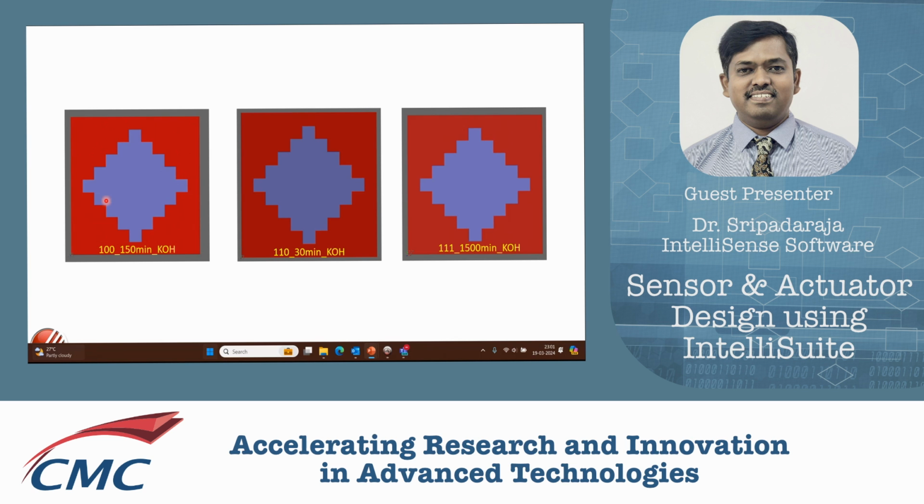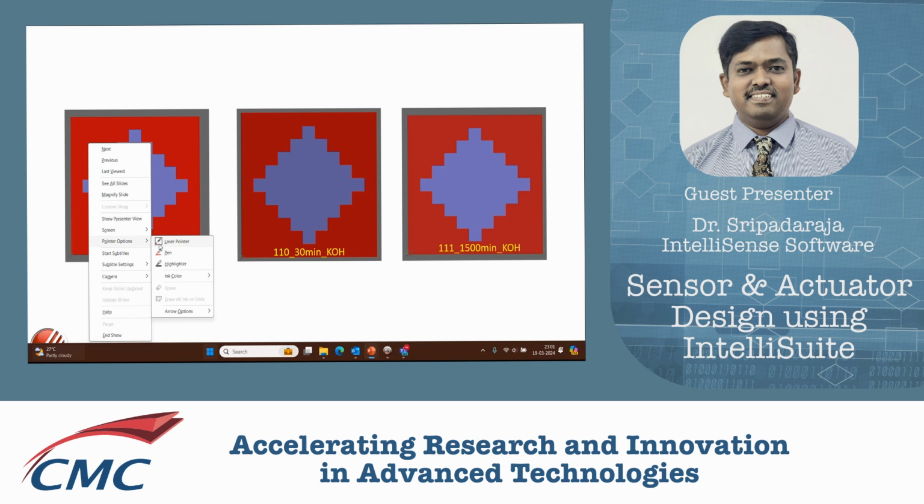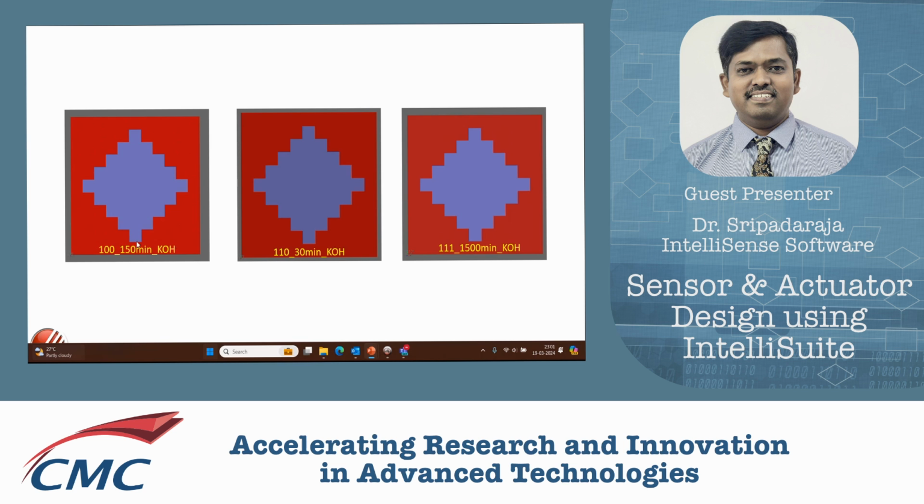Probably, I have to enable this video. Oh, yes, I got it now. Right. Okay, so here what we see is how the profile looks. What's the profile that is achieved with KOH etching with 150 minutes of etching on a 100 plane? And what really happens with 30 minutes of etching with KOH as an etchant on a 110 plane?